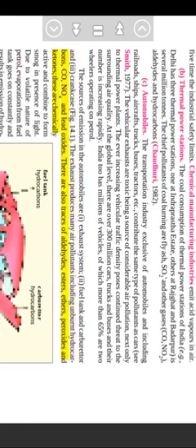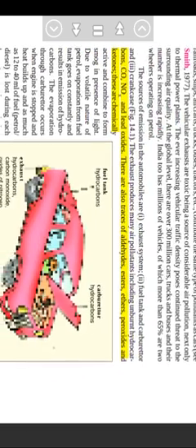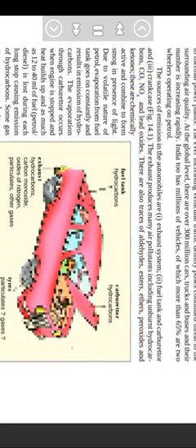There are also traces of aldehydes, esters, ethers, peroxides and ketones, which are chemically active and combine to form smog in the presence of light. Due to the volatile nature of petrol, evaporation from the fuel tank goes on constantly and results in emission of hydrocarbons.